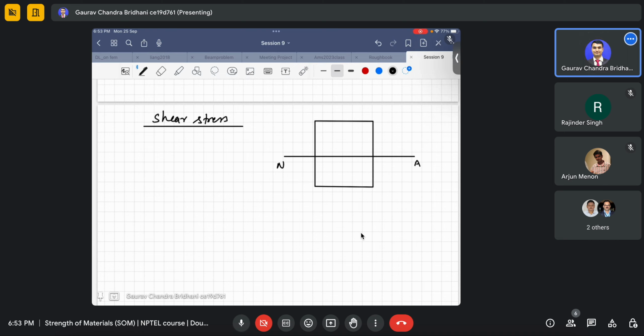And you know what the variation of the shear stress on the cross section is. Something parabolic, which is 0 at the edges and maximum at the center. Okay, that knowledge we have with us. It occurs maximum there. So we directly go to our expression which we just saw. We saw that tau xy is V q upon I zz into B. Now we'll find each one of these one by one.